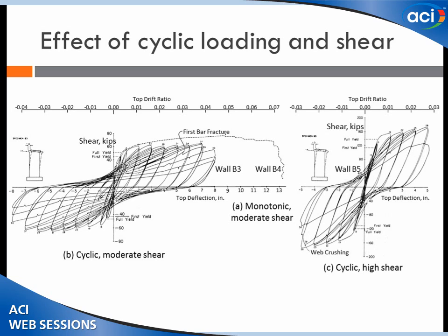There's a limit to what the shear stress can be in design, and most engineers design right up to that limit because they can, but without realizing that there's a price that is paid in terms of deformation capacity. So something still to be done maybe in the building codes related to Gene's contributions here.